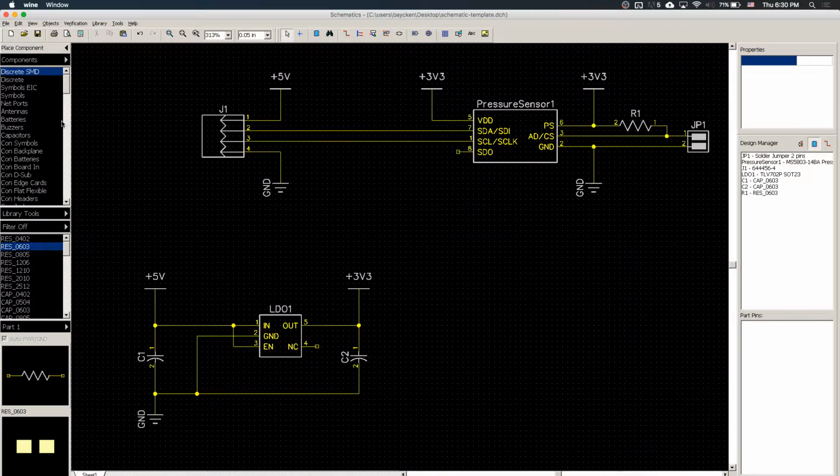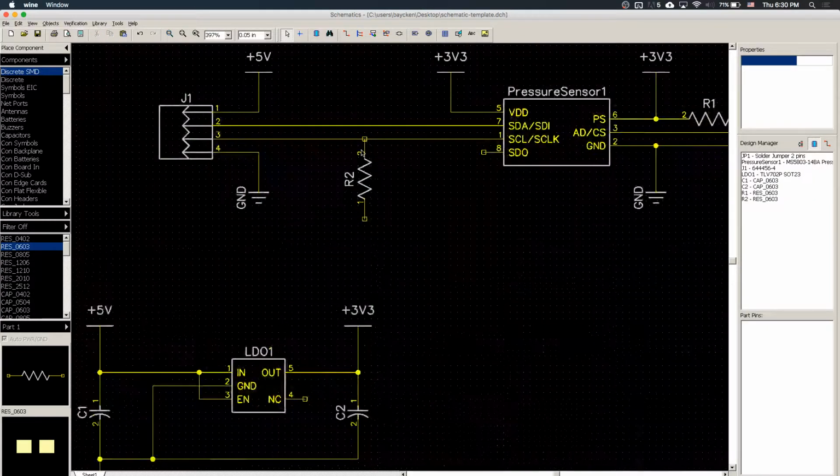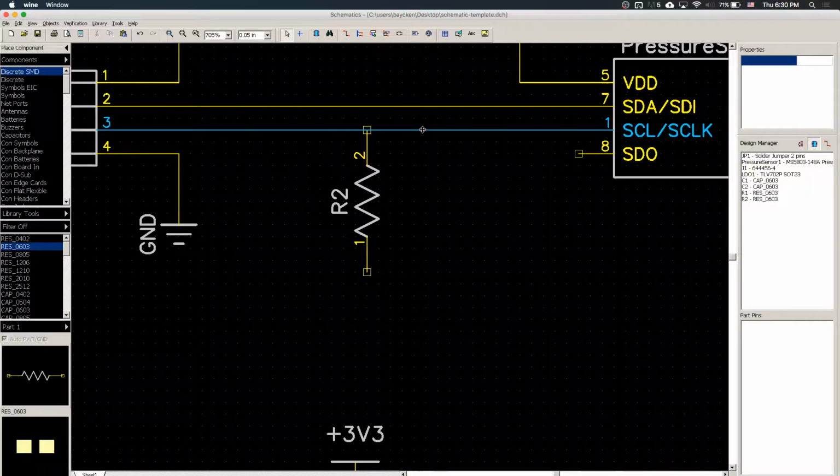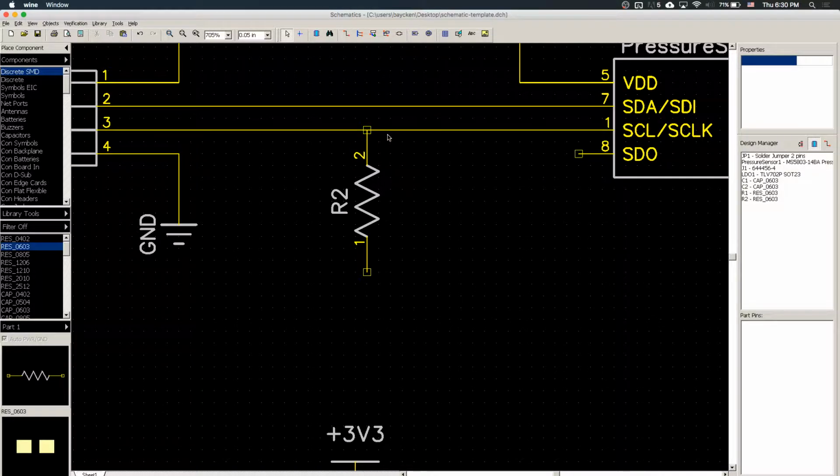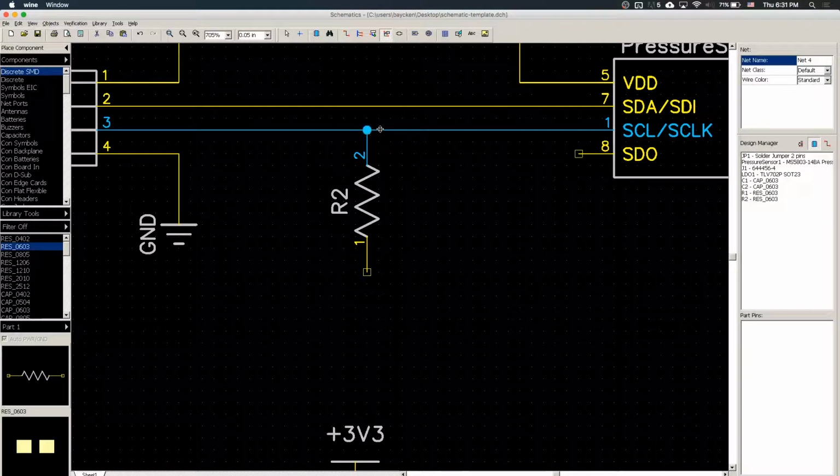One thing to note is that if ever you see a pin with a square on top of it, it means that it's not connected, although it might seem that it's connected to something. For example, if I place it here, it might seem that this resistor is connected to this wire, but in reality they're not connected. They're not registered as the same net by DipTrace. So if you actually want this to be connected to that, you have to make sure of it.